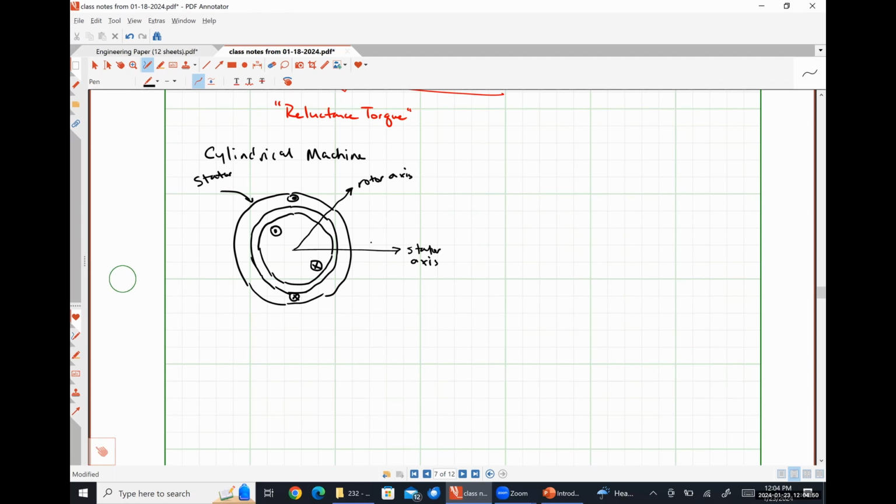And then this angle measured from the stator, which is stationary, to wherever the rotor currently is, is an angle theta that depends on the mechanical rotational speed, omega m, as well as time t, as well as this lowercase Greek letter delta, where delta is the rotor position at t equals 0. So think of it as effectively like a physical phase angle. If the rotor and the stator are perfectly aligned at t equals 0, then that angle delta would be 0 degrees. But as the rotor is more askew from the stator, that angle gets larger and larger. Okay.